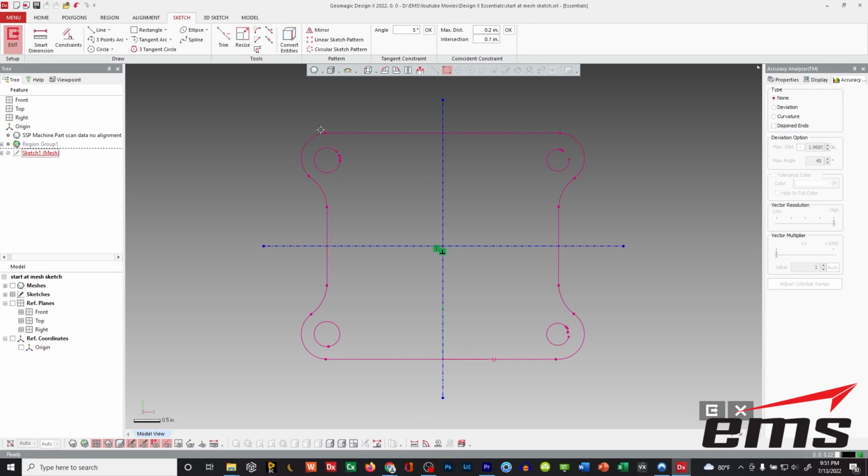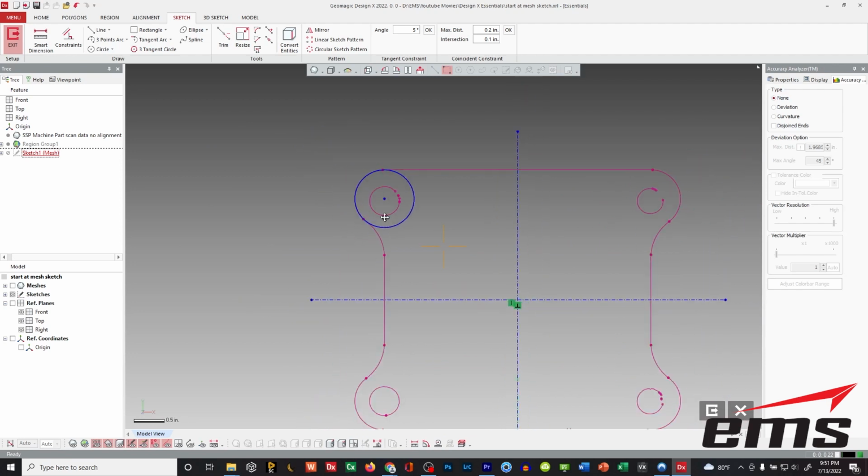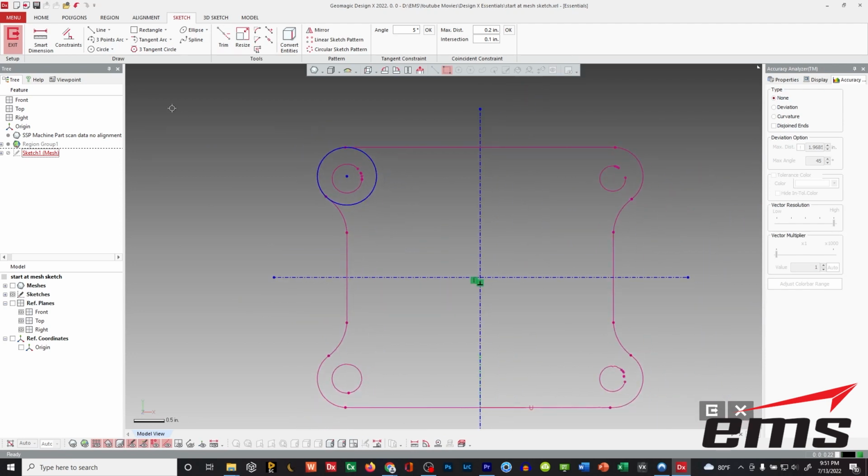So I'm going to start over here, and I'm going to pick the circle command. And you can drop a point and make a circle like you would in a CAD system. But what I'm going to do with this fit polyline on, and you see these points, this is a segment. You just pick it, and it is going to fit a perfect circle through that scan data. Pretty straightforward. You can take a look at it, say, yeah, that looks pretty good. Now, let's do the same thing again and pick that inner circle.